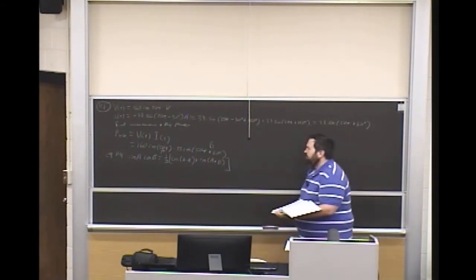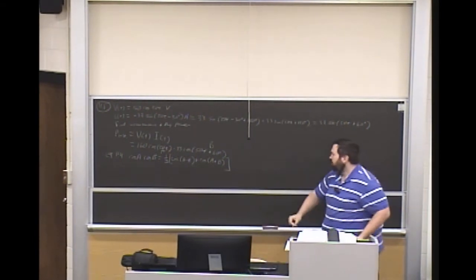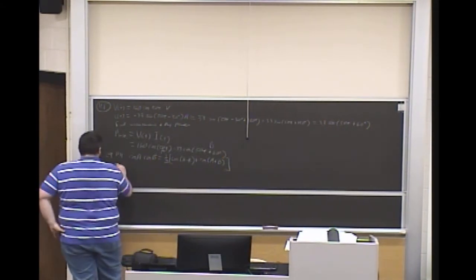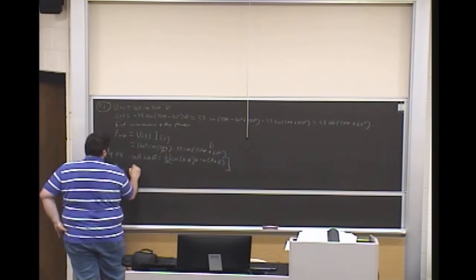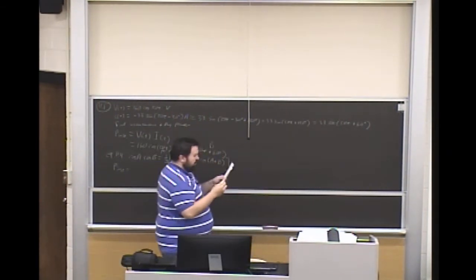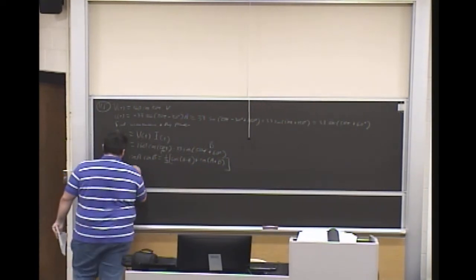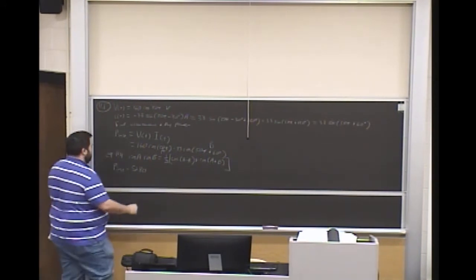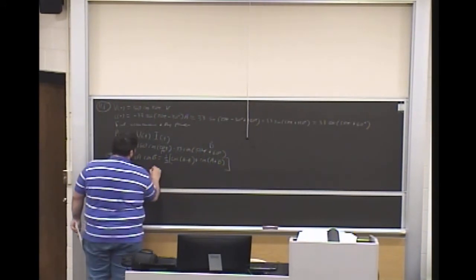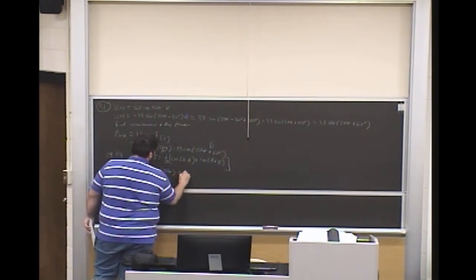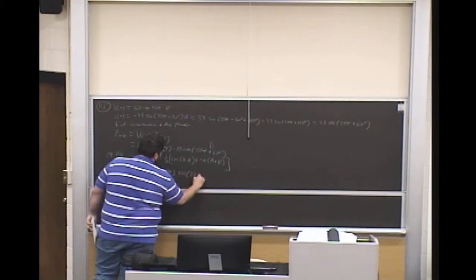And so now, as we're multiplying these things together, we can pull out the 33 times 160. So P instantaneous is going to equal 160 times 33, which works out to be 5,280, number of feet in a mile, coincidentally, times cosine of 50t times cosine of 50t plus 60 degrees.